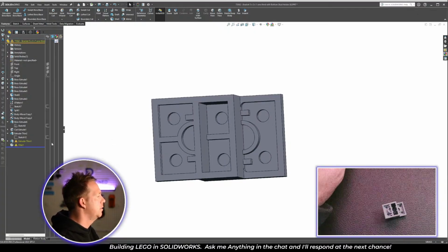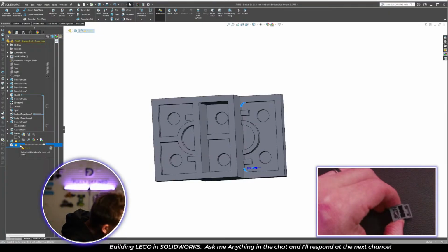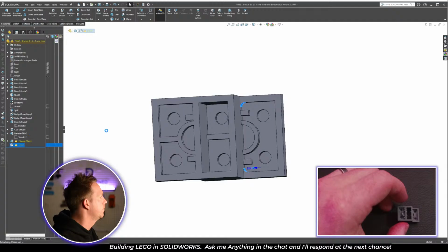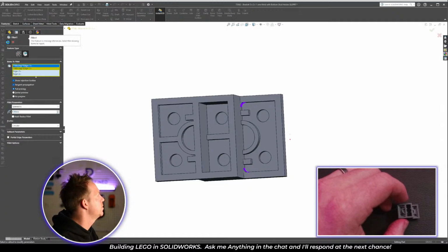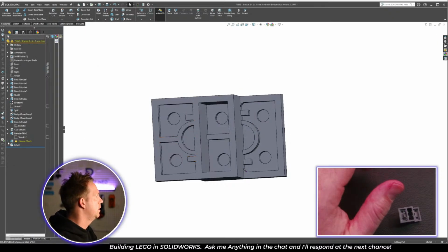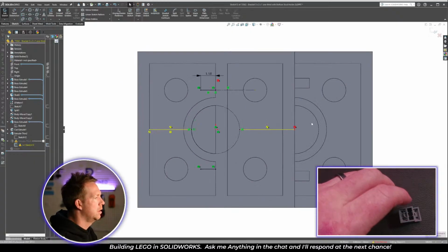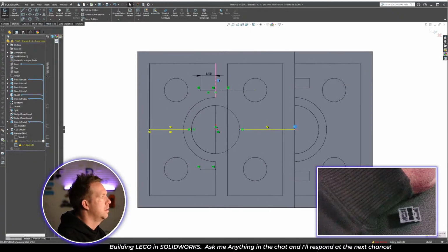Roll down. Do I need that little fillet? Yep, keep that little fillet. So just going to remove the missing references. Just press the tick, it'll do it for you automatically. And this last sketch to update here. Just tweak.